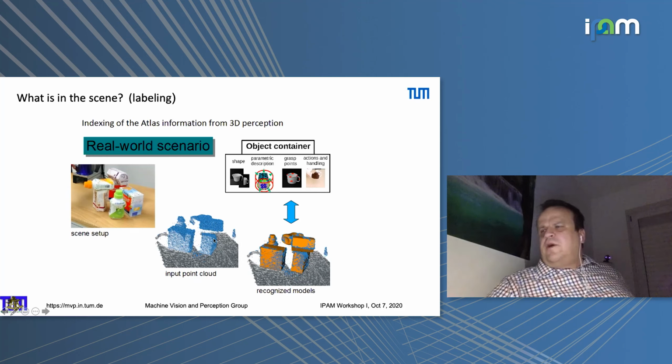It's using 3D information directly and a RANSAC system to fit different models. It has a set of 3D models in a database, and it fits these models in strongly occluded environments and gives you directly as an output the 3D pose of the object. So we use the shape to find the object in the scene.